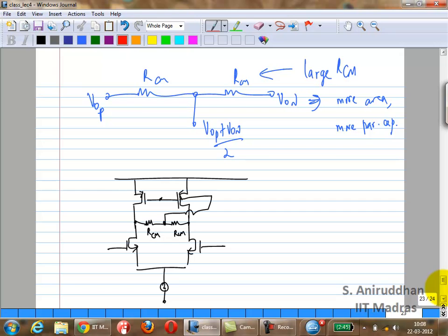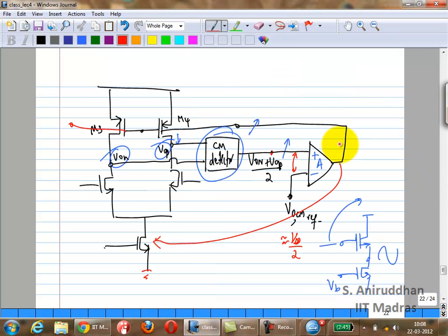And we found that the simplest case was using a resistive divider, right? Or rather not a resistive divider, it's just two resistors and you take the central point which gives you the common mode voltage. And we also found that the simplest way of adding this amplifier was to have no amplifier at all, right? This is the trivial case.